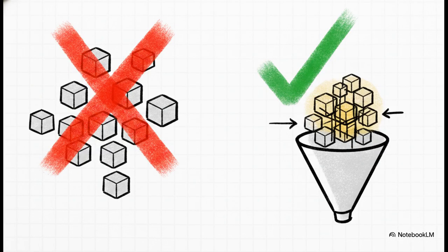Let's actually run a rapid-fire drill on this exact formula to see how we get to 1280 kilobits per second. Say the problem gives us a TDM link with 20 channels, so N is 20. Each is sampled 8,000 times a second, making f sub s 8,000. Each sample has 7 bits, so n is 7, and it mentions an additional sync bit, meaning A equals 1. Now, the fatal error students make is multiplying n, N, and f sub s, and then just tacking on a 1 at the very end. No, you have to add that sync bit A to n first. So it's N, which is 20, times f sub s, 8,000, times the total bits per frame, which is 7 plus 1. That gives us 20 times 8,000 times 8, which is 1,280,000 bits per second, or 1,280 kilobits.